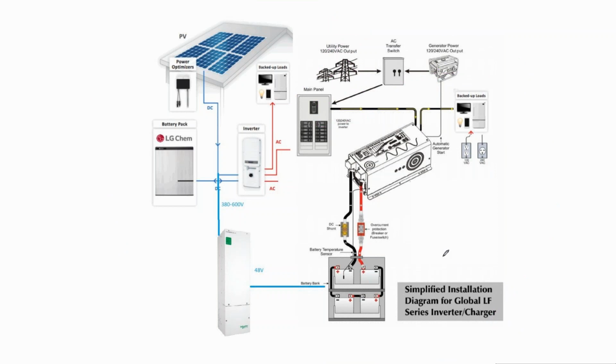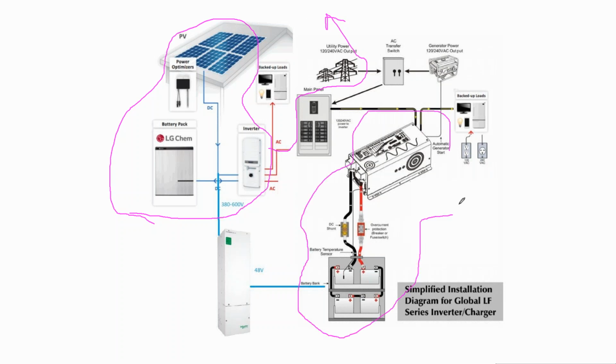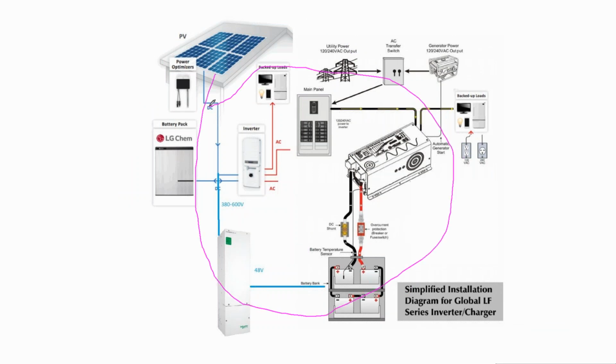And an elegant part of this system is that you can still use today the expensive grid-tied lithium-ion inverter backfeeding to the grid. And then if your grid policy changes and you want to do an off-grid conversion, that's when you would add the cheaper, not made for grid connection battery inverter with your flooded lead acid battery bank. And you achieve an element of double redundancy without simply buying two of everything involved.